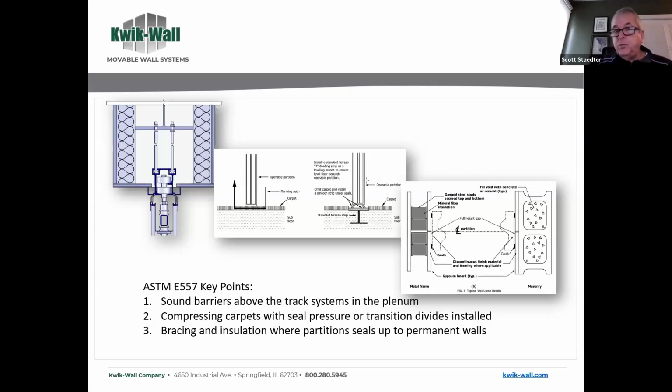And the third area is that when you put a panel in place, you want to make sure that there's bracing and insulation on the wall, the drywall here. Now you might be putting it up against a concrete wall, right? And if you want really ultimate, you put a jamb, and behind the jamb, and I'm not showing it close up, there's a break that doesn't allow the sound to transmit through that, right? So that's when you're really looking for high-end field acoustics.